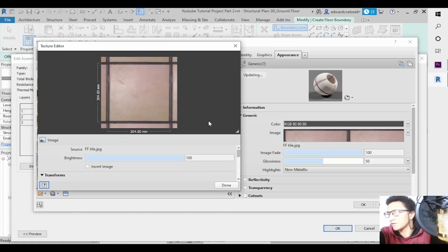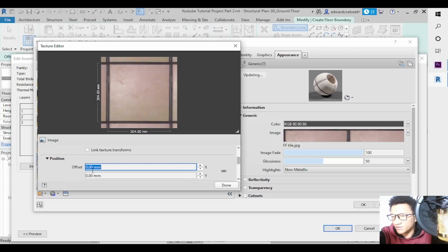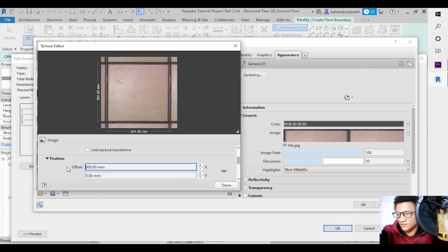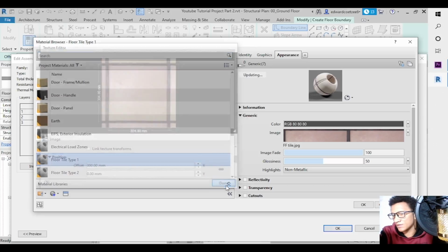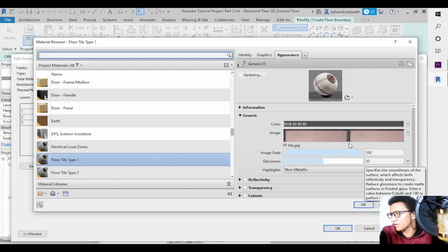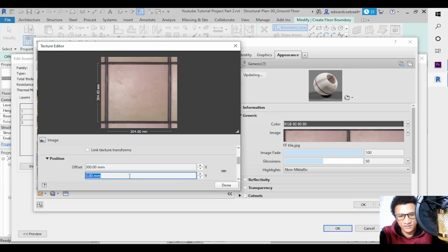When you click on it again, this is going to open, and you just want to change the size. So I'm just going to make it 300 mils. Copy that, say done. Okay, let's go and check again.